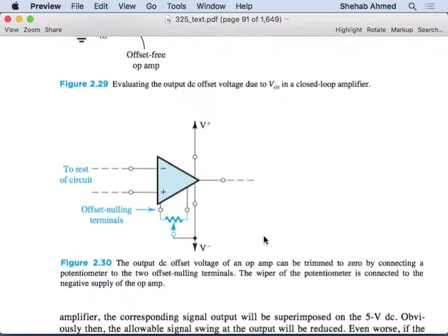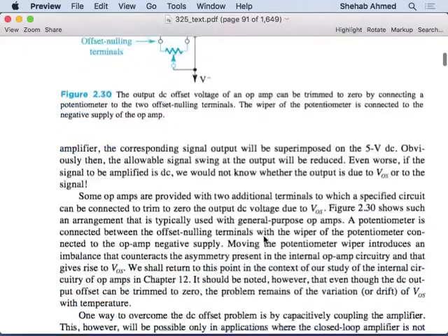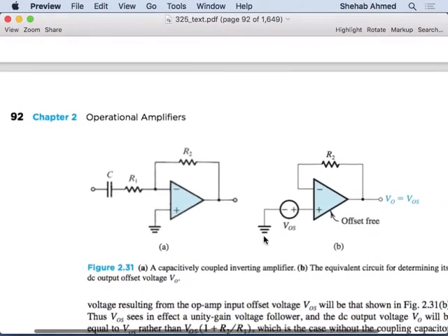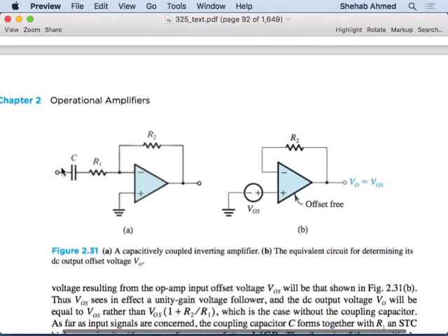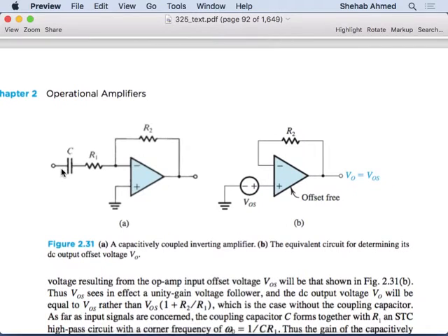One interesting way to deal with it, though, is what? This is a DC, right? So remember we talked about capacitor coupled amplifiers versus DC coupled amplifiers? So this is an interesting place where, fine, it would have been nice to be able to capacitively couple your amplifier. So one way to go around that is to put an input capacitor here. If I put an input capacitor here, what's going to happen to any DC components?